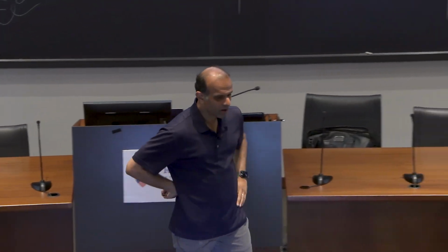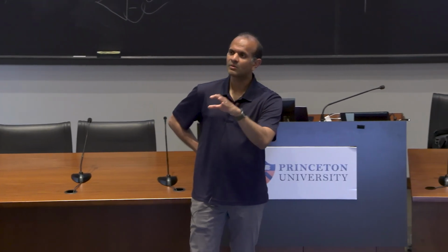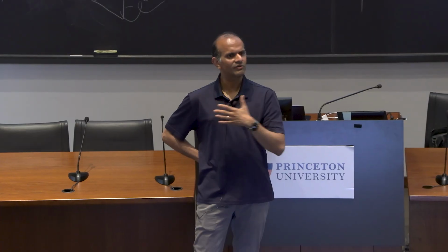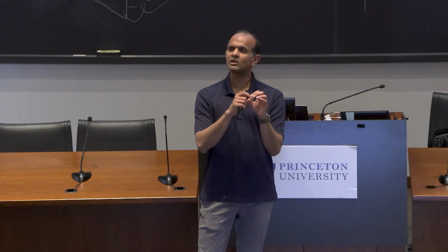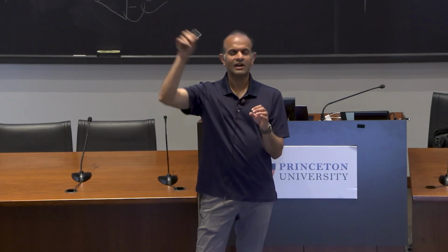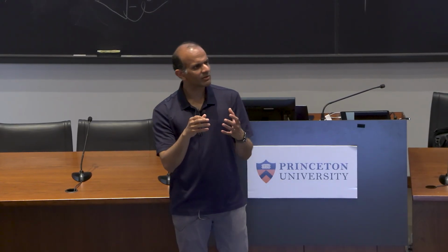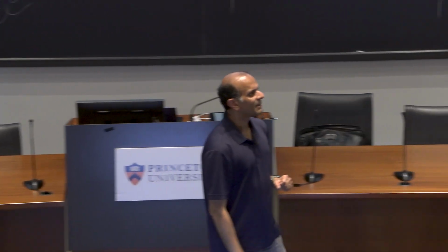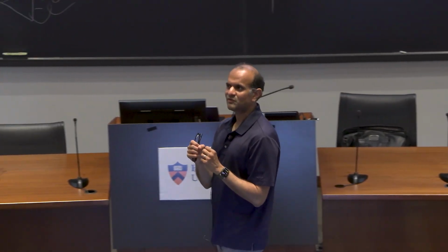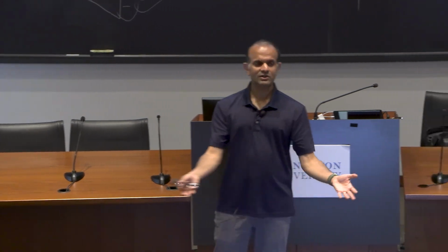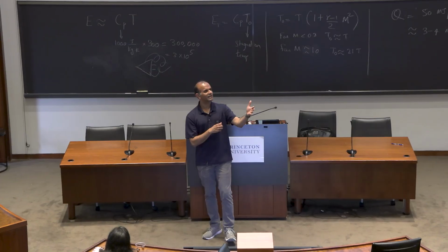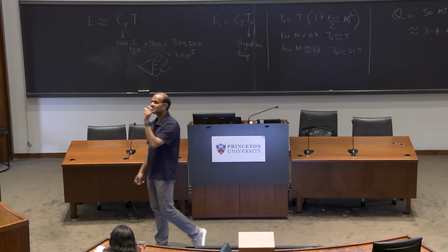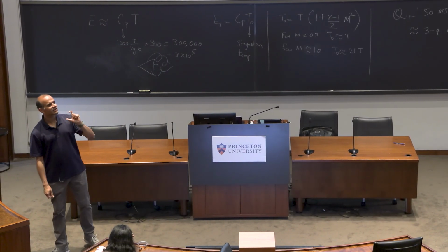Now, what we know from droplet evaporation theory, which Professor Matlon will cover tomorrow, I think, or Friday or something like this, is that there is a particular rate at which droplets will evaporate. And you can control it at some level by heating the droplet, things like this. But there is a rate. If you suddenly expose the droplet to a high temperature, it doesn't mean it immediately evaporates. It's not like that. It still takes a finite time, okay? That time matters. So we'll come to that repeatedly.